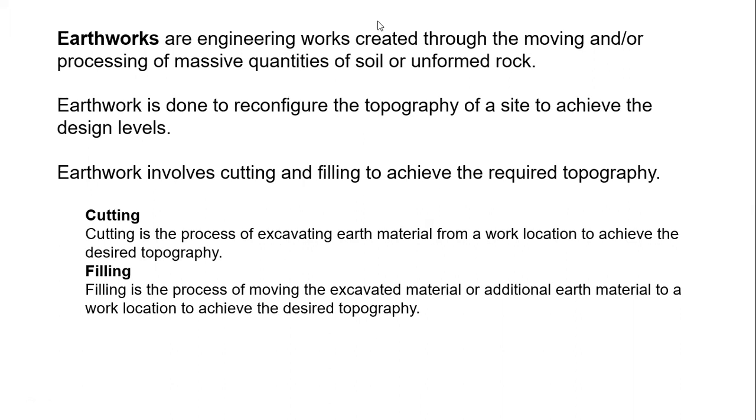So for example, let's say this is our natural topography, and let's say we want to construct a road with this geometry. Of course, we need to cut this part, and we need to provide slope protection if it's a roadway. So we will cut that, and of course, we need to provide the necessary fill materials for this.